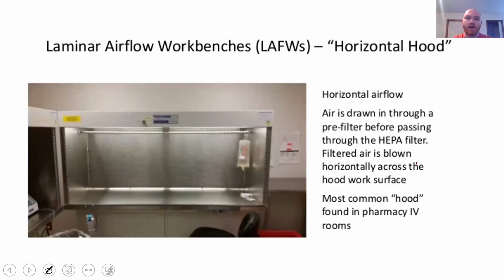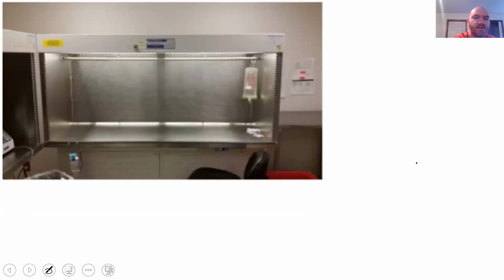So LAFWs are the most common type of hood in compounding pharmacies. And the way that these work is you have laminar airflow. Laminar means that it's all in one sheet. Everything is the same speed. So if we look at this from the side,